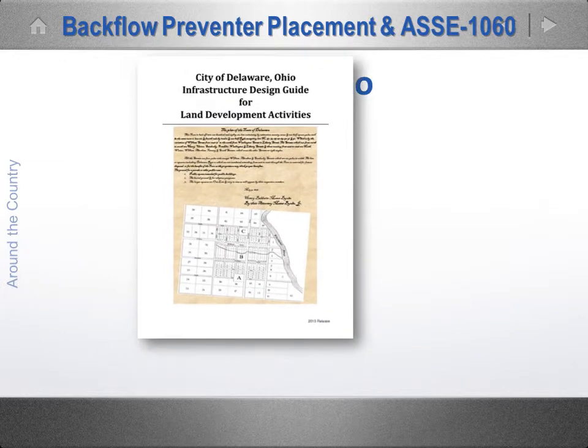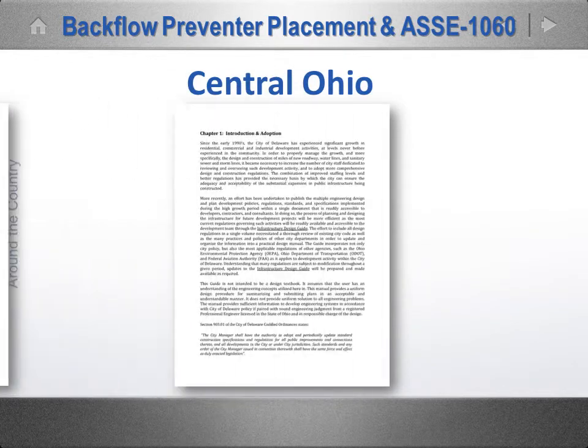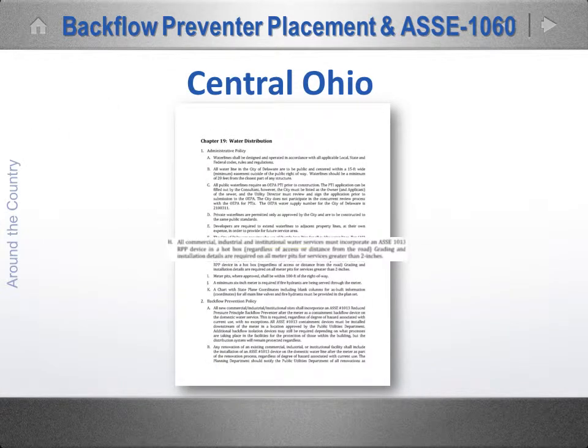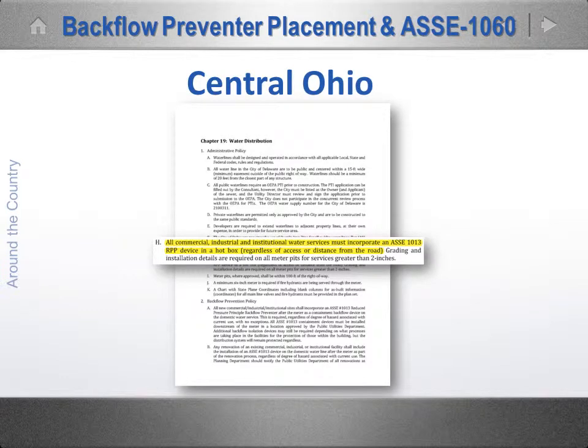Finally, Central Ohio, Delaware. In the 2013 release of their Infrastructure Design Guide, they now mandate RPZs in outdoor enclosures on all commercial and industrial water lines: domestic, fire, and irrigation. Changes like these are literally occurring all over the country.